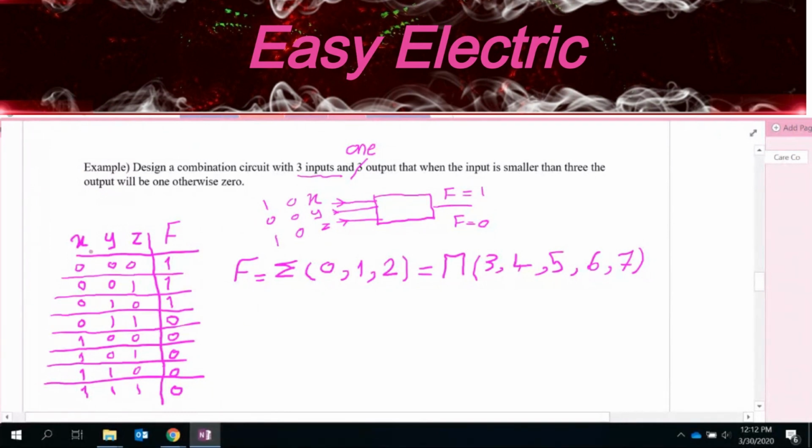So you just check this, you say, okay, 1, 2, 3. So this is 3 variables, so 2 power 3, 8. So you actually need a K map with 8 squares, right? So you actually make this. We already did this type of work, right? So you put X here, y, z here. So put the 0, 1 for this: 0, 0, 0, 1, 1, 1, and 1, z. So just write the numbers for each of these squares.